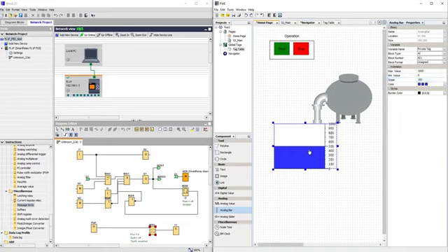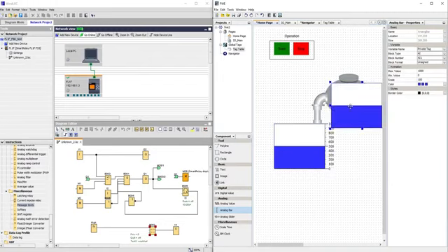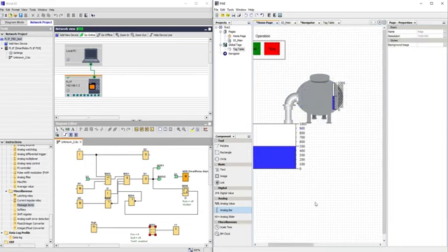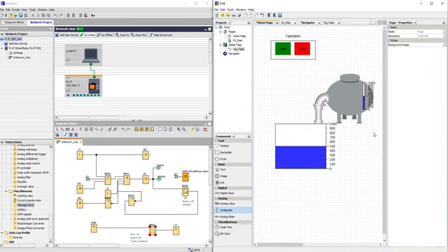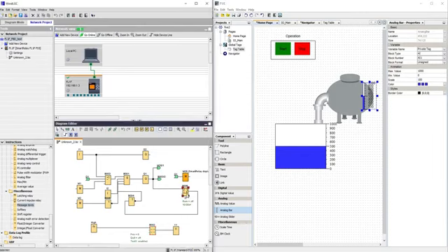So similarly, I'll take one more scale over here, copy and paste for the tank status. So let us take this as a tank status. So here also I need to enter the values as 1000 and 100. Now we have to link these values to the timer value. So I'm considering a timer here.